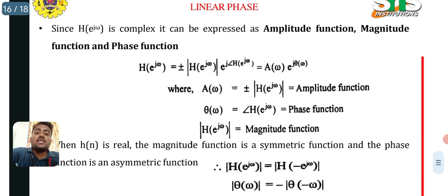First, we have to know what the limits are for ideal filters, which means ideal low pass filter, ideal high pass filter, band pass filter, and band stop filter. From that we can derive H_d(e^{j omega}), and the second step is to take the inverse Fourier transform to get h_d(n) with infinite limits.